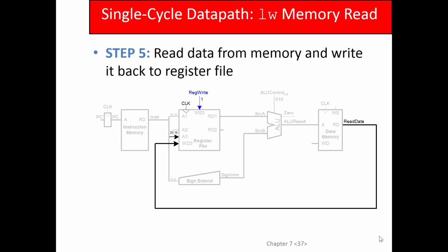Now these are all concurrent, by the way, there's no ordering here. But you can see that every cycle I'm going to do this operation which updates this signal, and then this guy is going to get triggered because the IR updated, right? So this is the way that you would describe this in register transfer language.